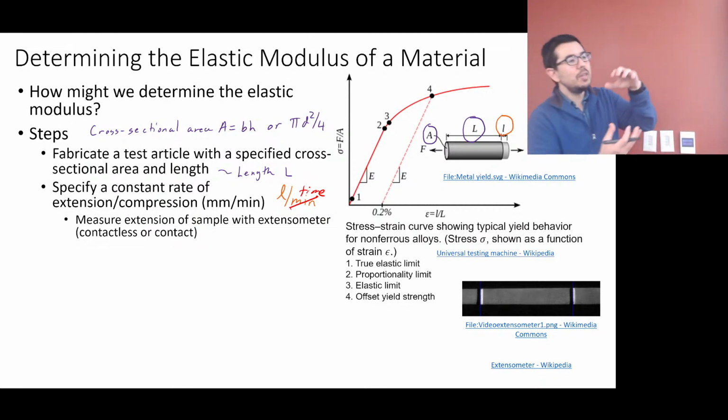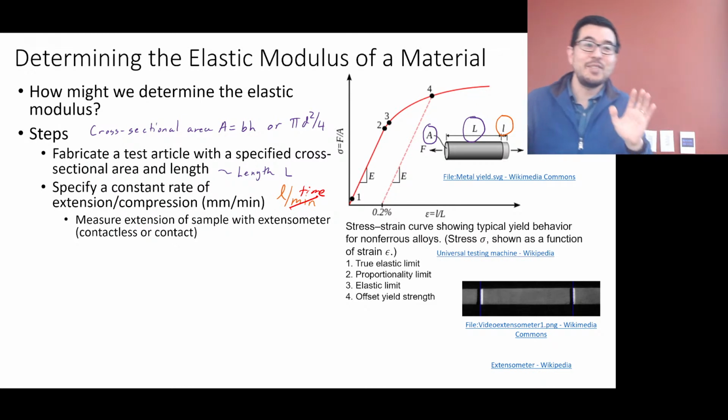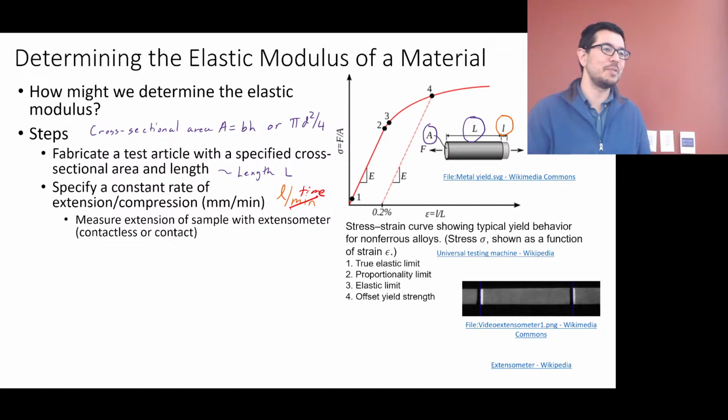And that's going to be the machine pulling this apart, but you need some way either to measure the extension with a video or images, or with an extensometer. Or, to be honest, if you're not too concerned about the precision, and the machine's not too big, you just use what the machine tells me in terms of displacement and call it a day.